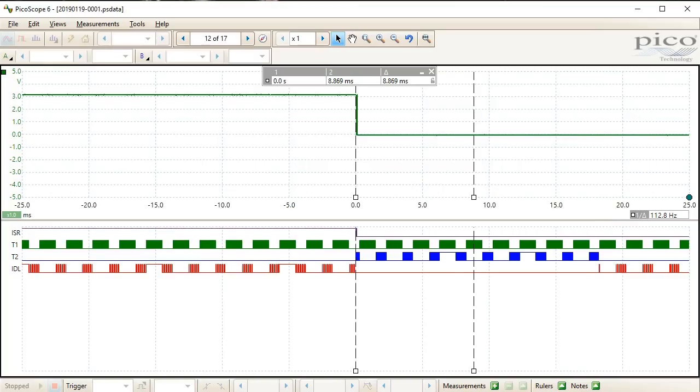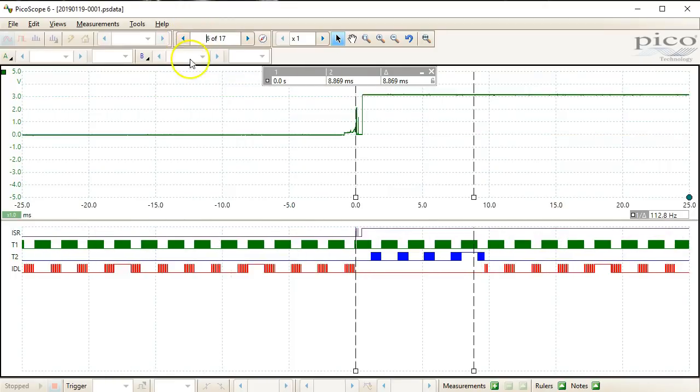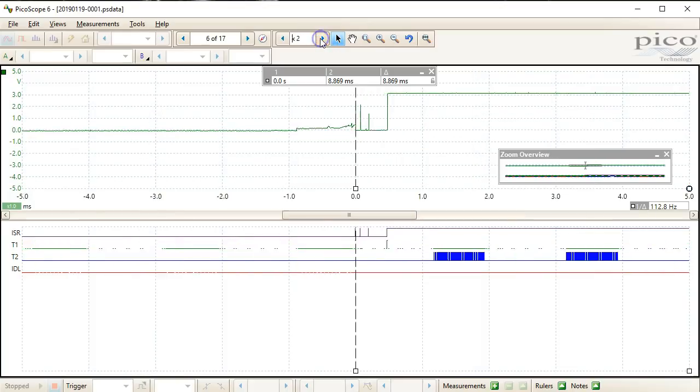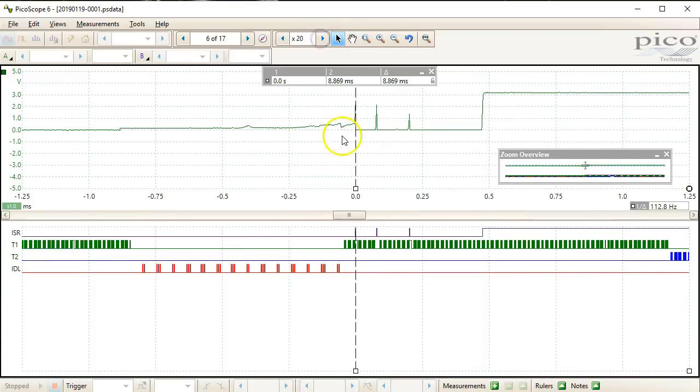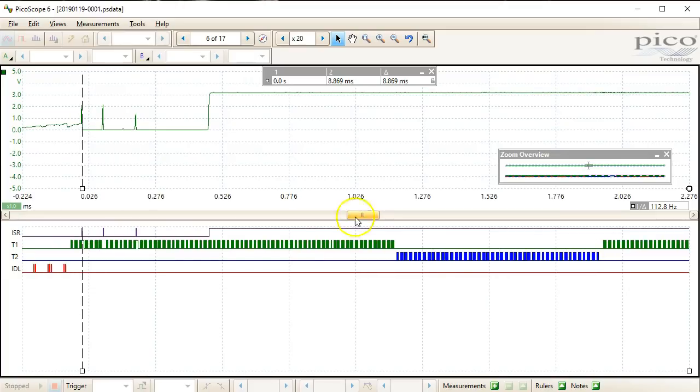But this is only one way the scenario can play out. It turns out that due to thread preemption, essentially the same 3 bounces of the switch can lead to quite a different outcome of Blinky2 going just once through its while(1) loop instead of twice. An example of such a scenario is trace number 6. Here, the switch bounced while it was released, as opposed to being depressed, but still it produced 3 falling edges, and, consequently, the semaphore was signaled 3 times.